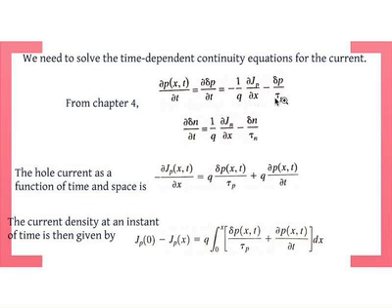Right? Recombination is proportional to the recombination probability, which is basically inversely proportional to the lifetime, 1 over tau p. Of course, it's also proportional to the number of carriers that are there. Recombination probability depends on how many carriers are there to recombine, divided by the lifetime of the carriers. Okay, so that's that term. It's a negative sign because it's getting rid of the carriers. It's decreasing the carrier concentration.